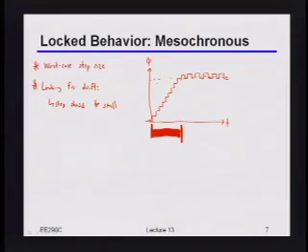Doesn't making the step size small affect the time it takes for you to actually get to the right point? Yeah, absolutely, right? So indeed, if you make those step sizes very small and you don't do anything else, then initially when you have to cover a very big distance, it's going to take you a long time to cover that distance. But imagine that now once I'm in lock, basically the only thing that tells me how big to make these steps is how big the residual errors I'm trying to track in the first place were, right?